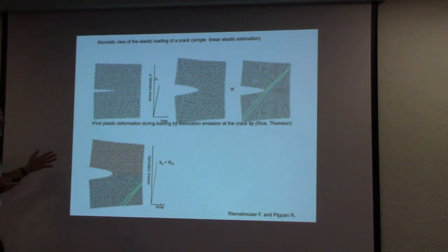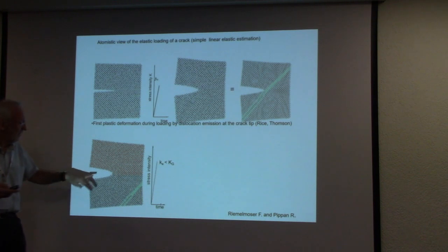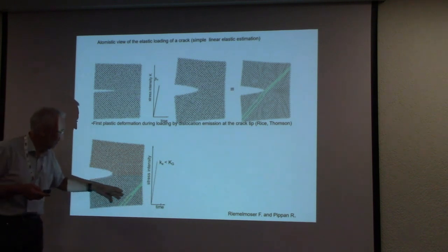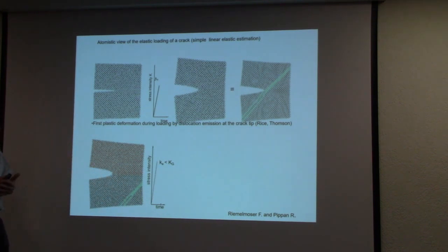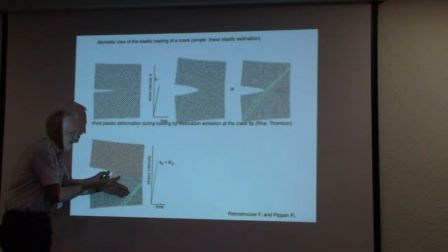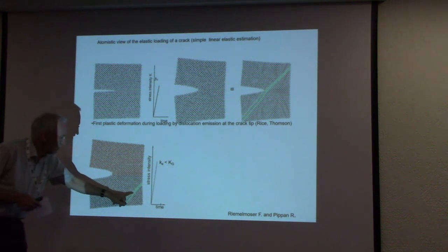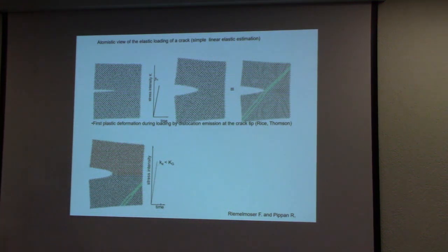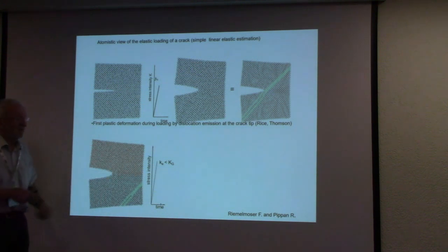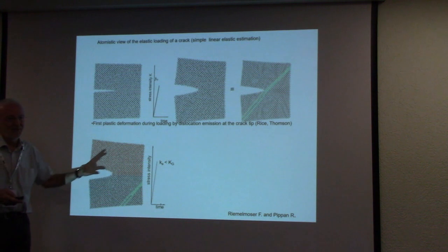But in this case, the only thing we have already done, and have sometimes used, is to calculate the stress which is necessary to move the dislocation at 0 Kelvin, or to look at the structure of the dislocation. You can do that. But it is not possible to really describe plasticity in a unique way on this scale.